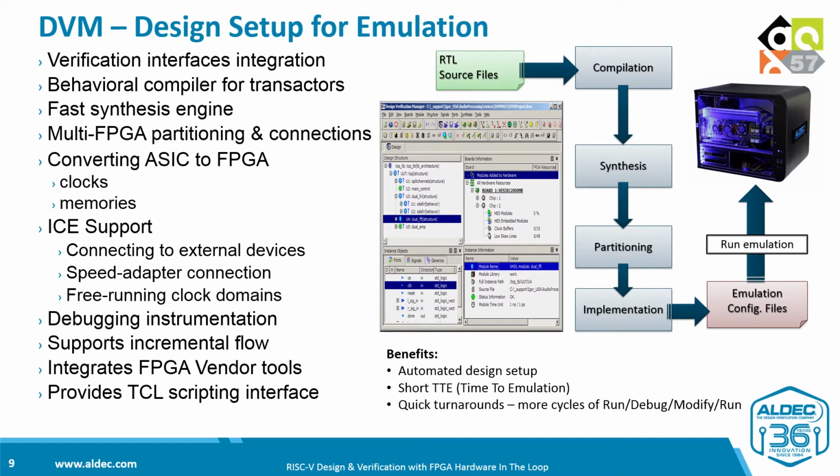So let's talk about the software components that come with hardware. DVM, which is Design Verification Manager software tool, is for design setup automation. It will guide you starting at RTL source compilation through synthesis, partitioning and FPGA bitfile implementation. DVM provides two distinctive design flows, one for emulation and the other for prototyping.